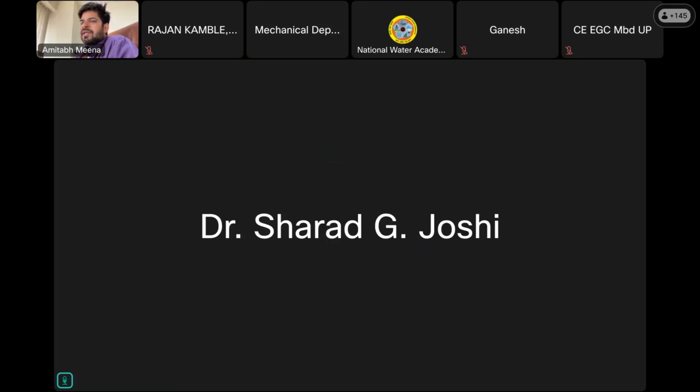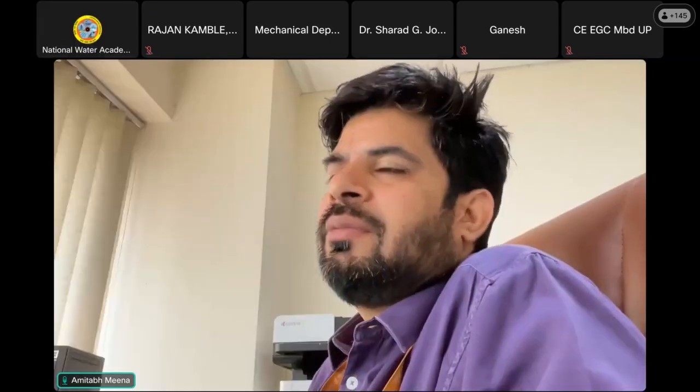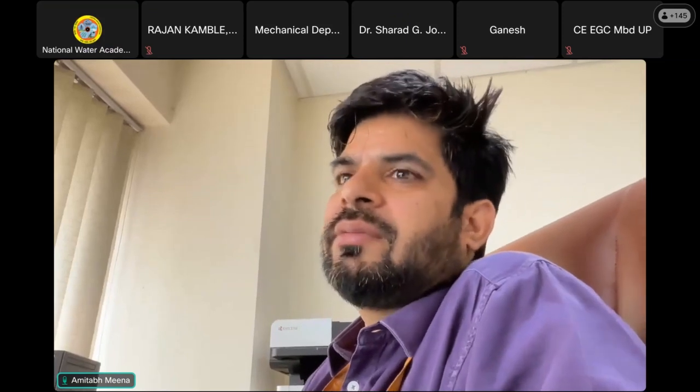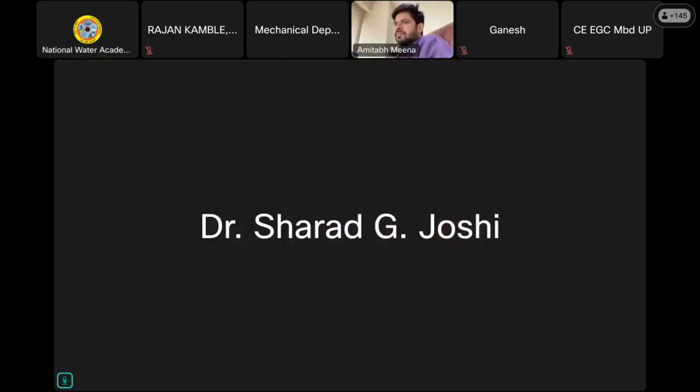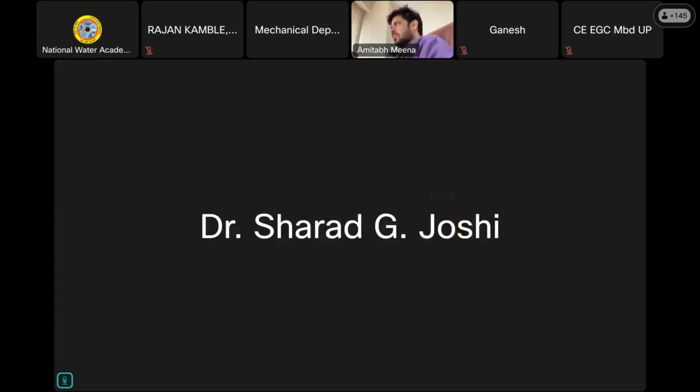Is it for embankment, earthen dams, or what? It's general for every structure. But we have to specify for each type of dam because they vary hugely. Correct. And again, when we say Lugeon, it depends on the head of the water also. All these things are built in. So it specifies 2.5 to 5 Lugeons. Normally we practice that if it is more than 5, then suggest treatment immediately.